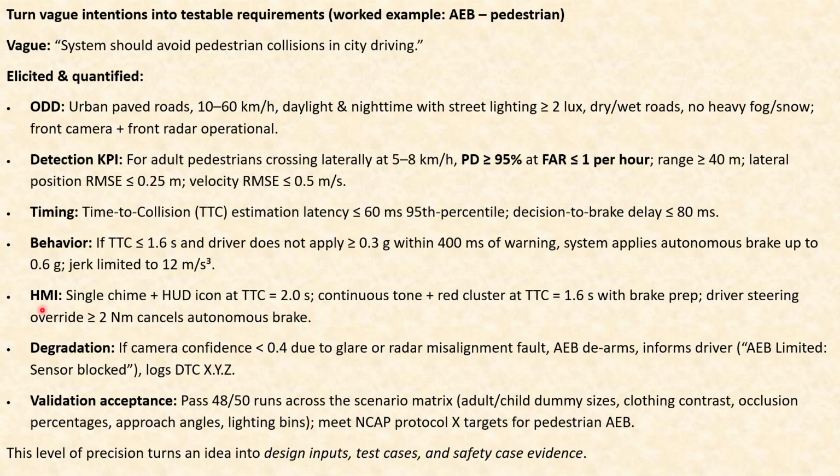And when it comes to the human-machine interface: a single chime plus HUD icon at the driver display at TTC 2.0 seconds. Then a continuous tone plus red cluster at TTC equal to 1.6 seconds with brake preparation.